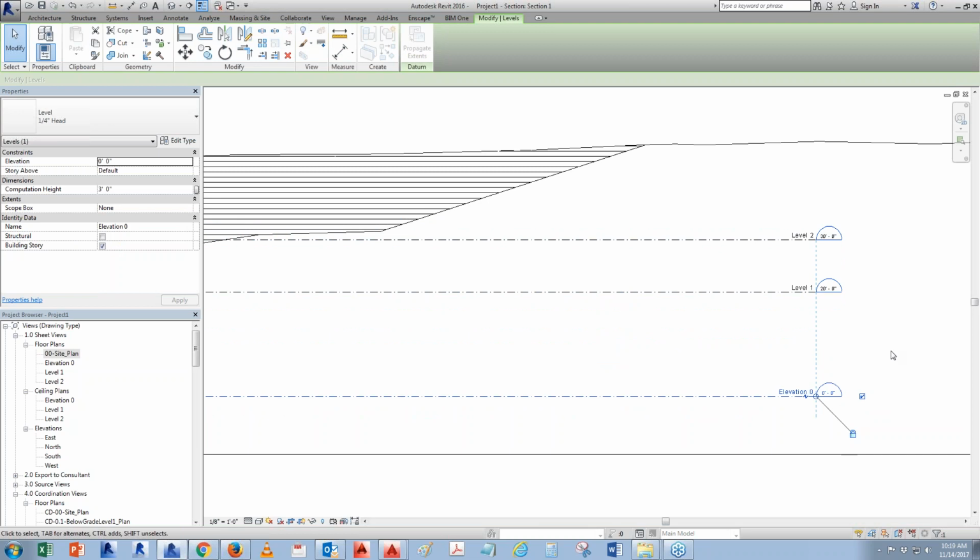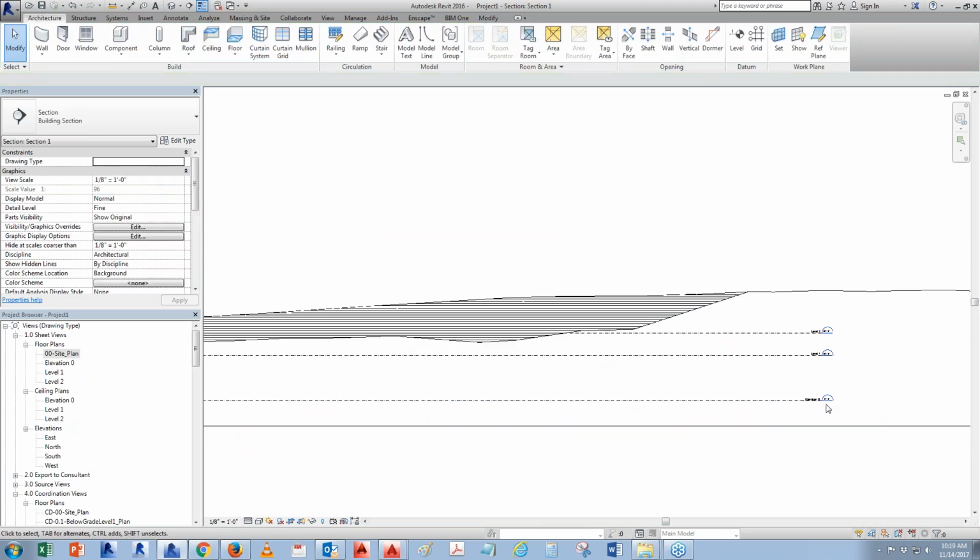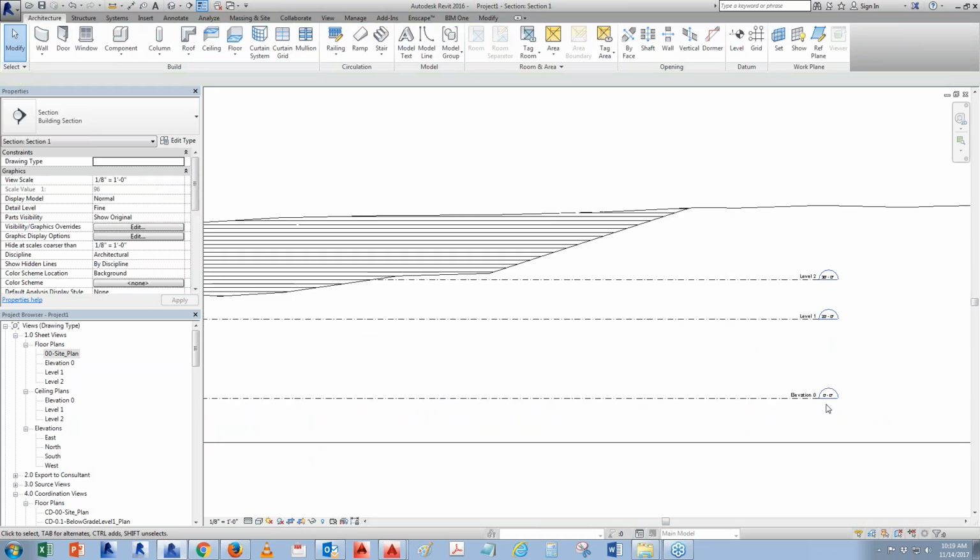And this one, I like to put it at 0. Okay, so this is going to be the absolute 0. Now, if someone screwed up with your camera, when you copy it, I always say paste it to elevation 0 so that the camera itself, if you copy from one Revit project to another, if you have that elevation 0, it will basically place it in the correct location.